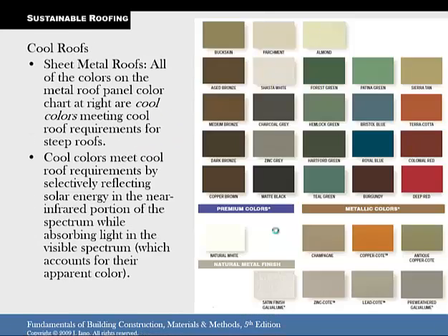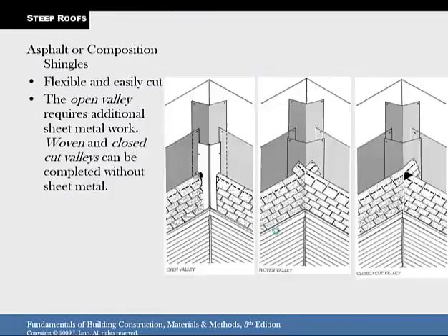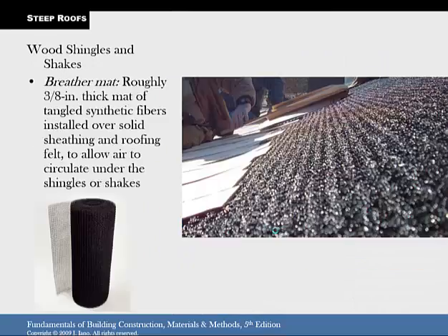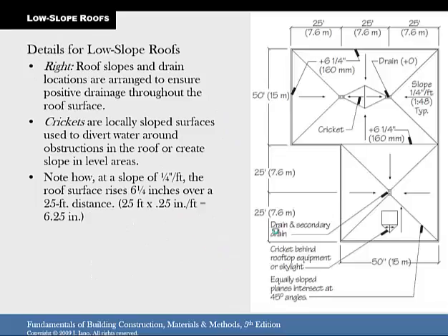On this exercise sheet, let me go back to that picture. There it is. On the roof plan, this is a slightly different roof plan, but the one on the bottom is kind of similar. For number 1, it says, on the roof plan to the right, add arrows indicating a slope. Assume a slope of 1/4 inch per foot and label the roof high points.